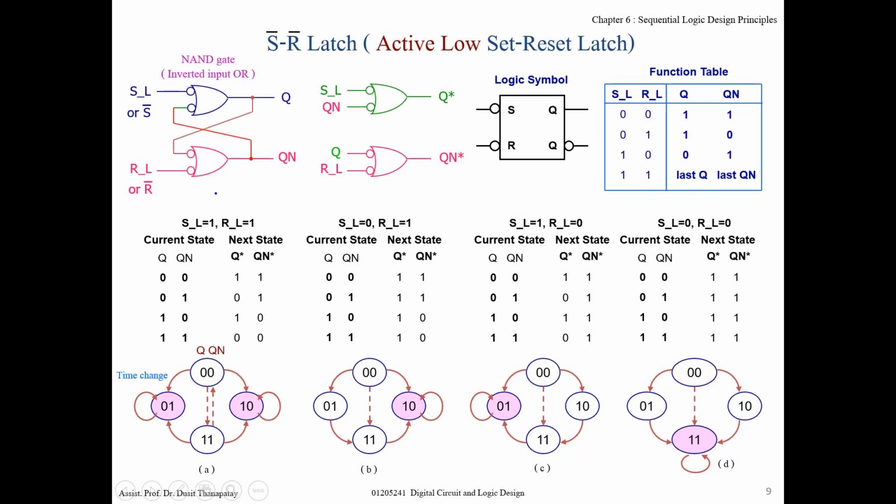this circuit will be bistable when you apply 1 here, 1 here. Maybe one inverts, right? It becomes 0, then all this one. So it becomes Q prime here. And for this side, Q is 1, then inverted becomes 0 here, or Q prime. So it becomes bistable when S is 1, R is 1.